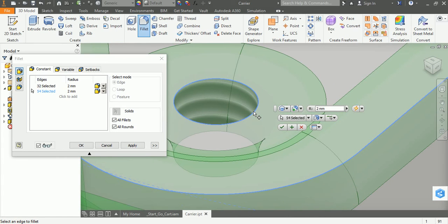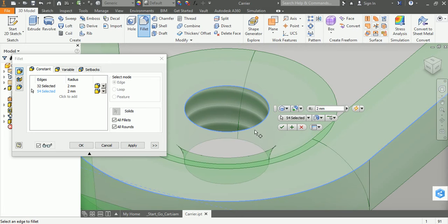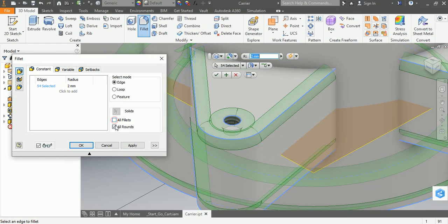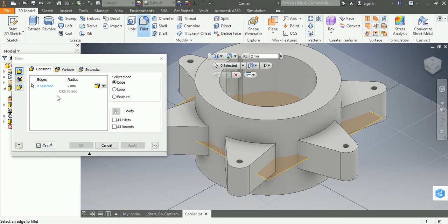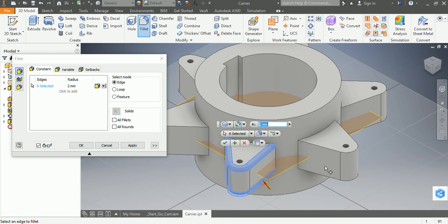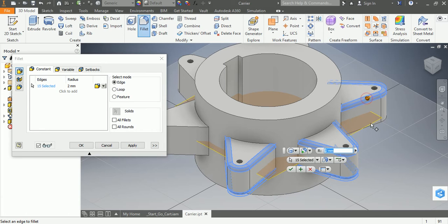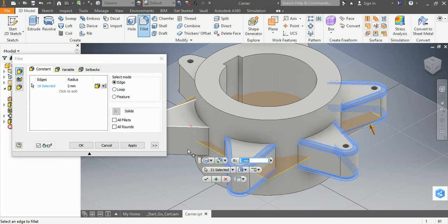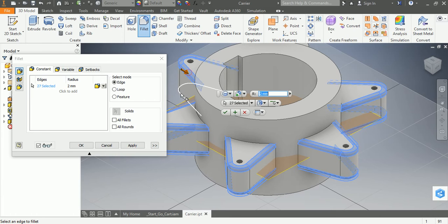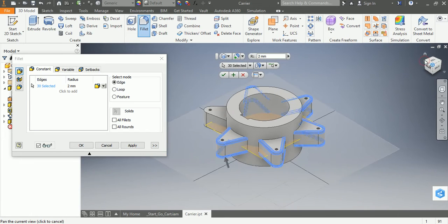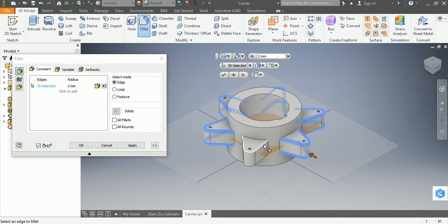And I actually don't want it at the circle. So you can shift click. Okay, you know what? This will be quite messy. So let's do it manually. Select all the parts you want to get filleted. Yeah, it can be kind of tedious. There was an easier way to do this, but I messed up actually by making the holes.